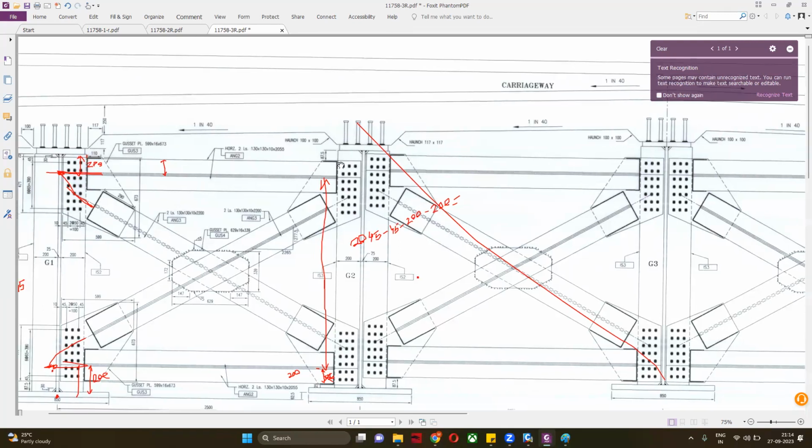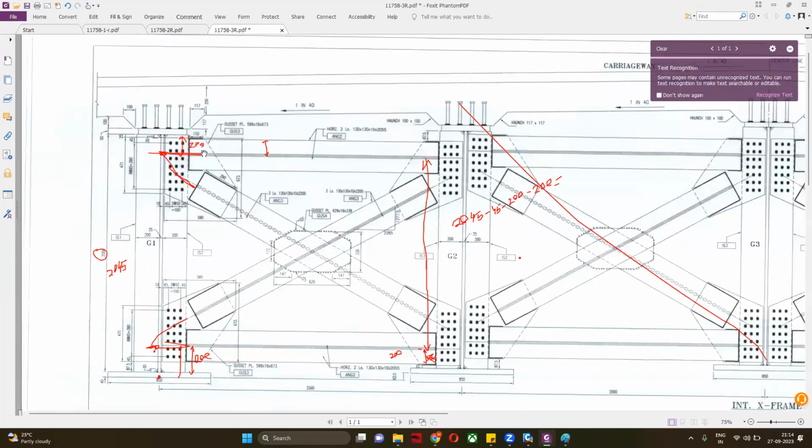Another case is that if some wind load or earthquake load comes from the longitudinal direction or maybe the transverse direction, the whole bridge will behave as one part, not different parts, because the slab will not make our girders act as one, bracing will.